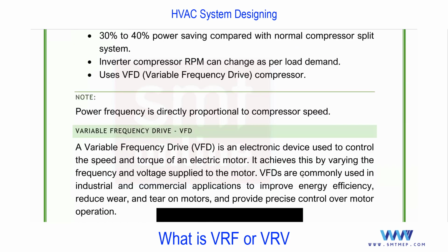So remember, if the power frequency changes, then the speed of that compressor also will change. And the same concept is applicable for pump and fan. And why am I adding pump and fan? Because this same VFD concept you'll find at the time of pump selection as well as fan selection. In pumps, if you talk about the secondary pump, it is a variable speed pump. And even in a VAV system, the fan motors are variable speed drives, nothing but with a VFD drive. So this concept is important.